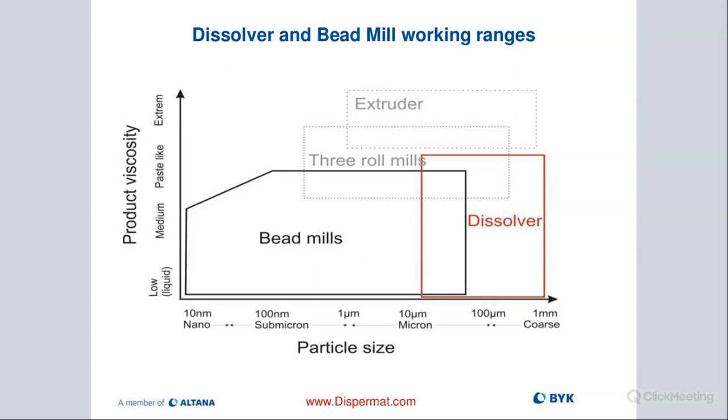And then with the bead mills, we're able to go super small. Also, we have some applications where we want to go below 150 nanometers. And with the bead mills, with the right bead mill design for nanoparticles, that is easily achievable. But you need to, of course, again, have the right setup.